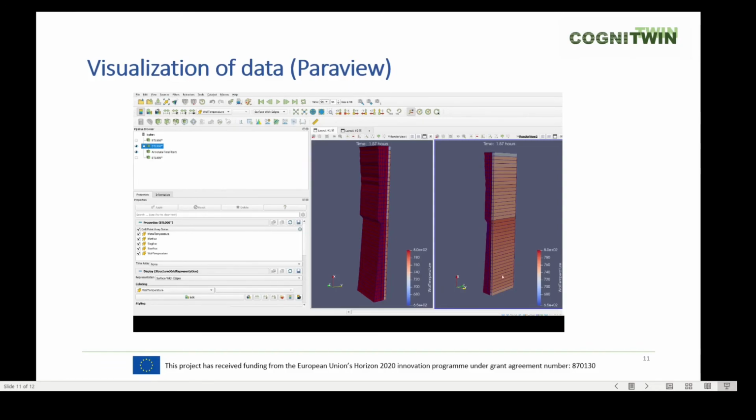So it's slightly cooler at the lower part and slightly hotter at the point where we have heavy erosion. So right now, temperature calculations indicate that at points which are thin, we should expect somewhat slightly higher temperatures. And this information could be used in conjunction with thermal cameras to say something about the state of the refractory.